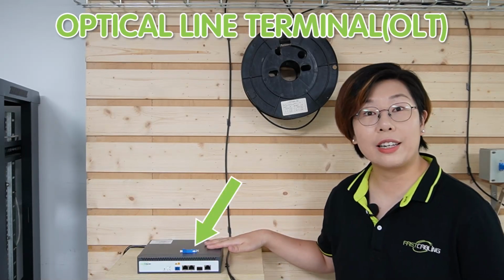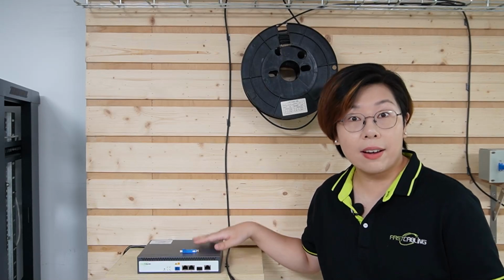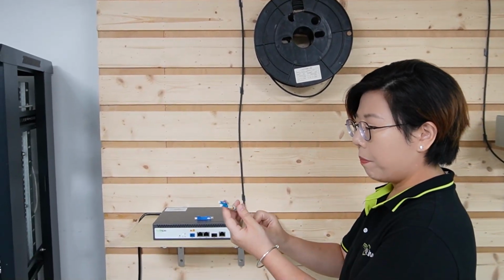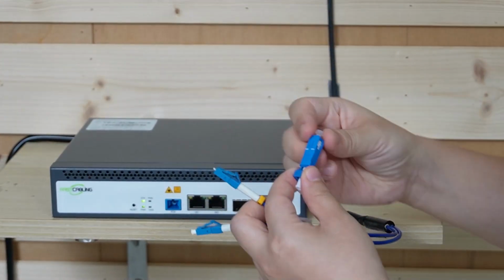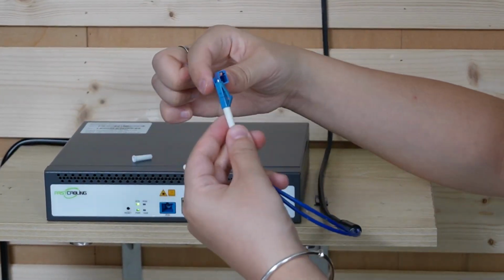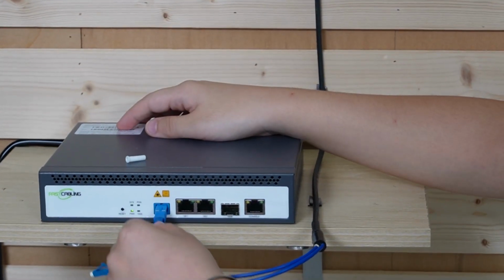And next, let's connect the main fiber string from our splitter's input port to our optical line terminal, or you can call it OLT. Now think of the OLT at our control center as the device that manages your entire network. So this is the same fiber optic cable. Remember, we use string A. So let's connect it to our OLT, and to the PON port.